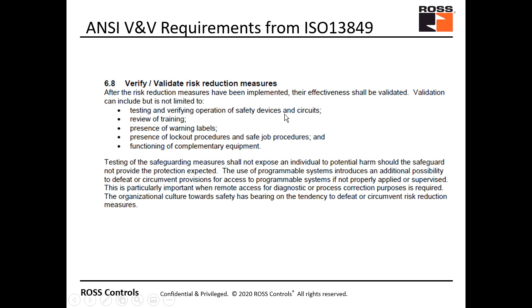Testing and verification of the operation of the safety devices and their circuits. And look here, that testing should also have looking at the possibility of defeat. So what this means is you should also be doing fault injection. What happens if I lift on a dual channel system? What happens if I lift the A channel wire? Did the system stop? What happens if I short channel 1 to channel 2? So there should be verification and validation, which includes fault injection.